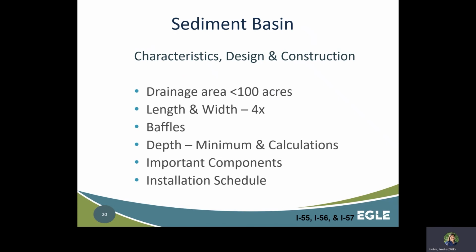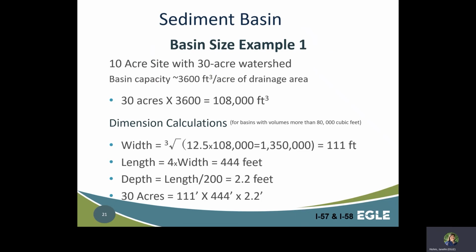Sediment basins should be constructed before any other land clearing or grading is done. If a sediment basin will be converted to a permanent stormwater basin at the end of the project, require the contractor to perform needed maintenance on the basin, including dredging. Don't rely solely on your sediment basin for sediment control. Have appropriate erosion control measures and other sedimentation control measures in place on site for volumes over 80,000 cubic feet.